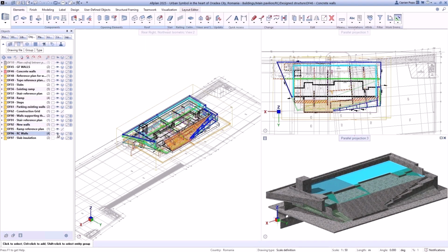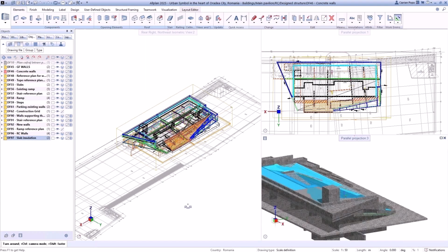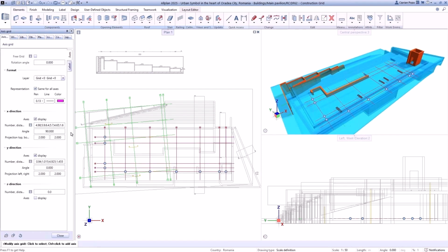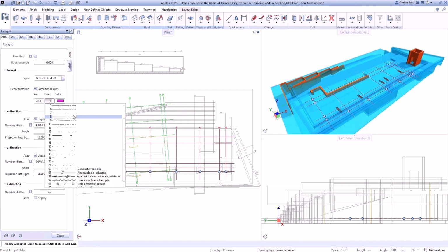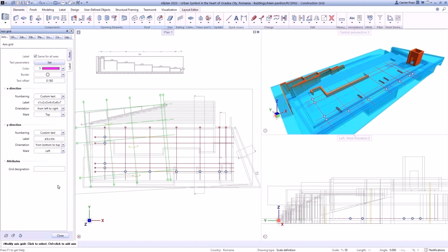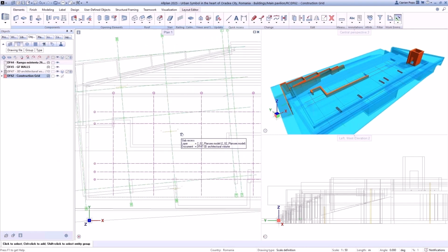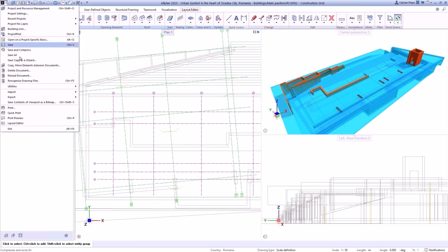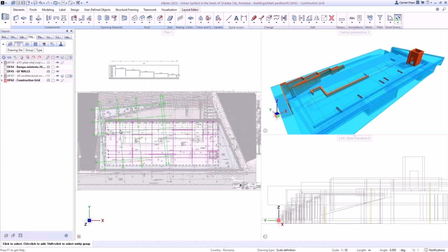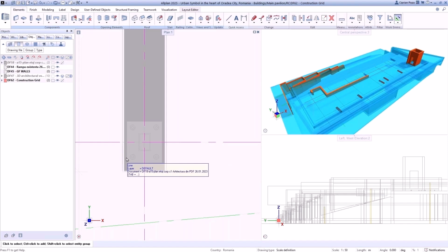So we have drawing files, we can use different layers or filters to see exactly what was built. And also we can use parametric data. There are many parametric objects like the grid system, which is also IFC compliant, meaning that you can transfer it within IFC models. And we all know the grid system is vital for alignment and for correlations. And of course, we can import the data even from PDF if we have scanned documents, or the architect just provided a nice PDF but could not provide us DWG.